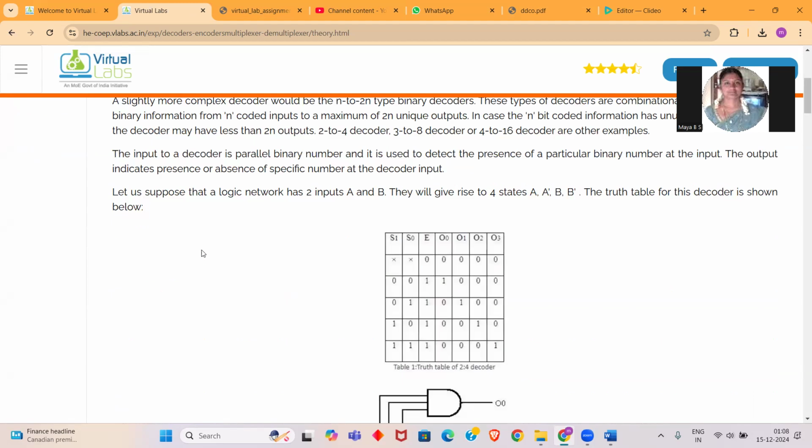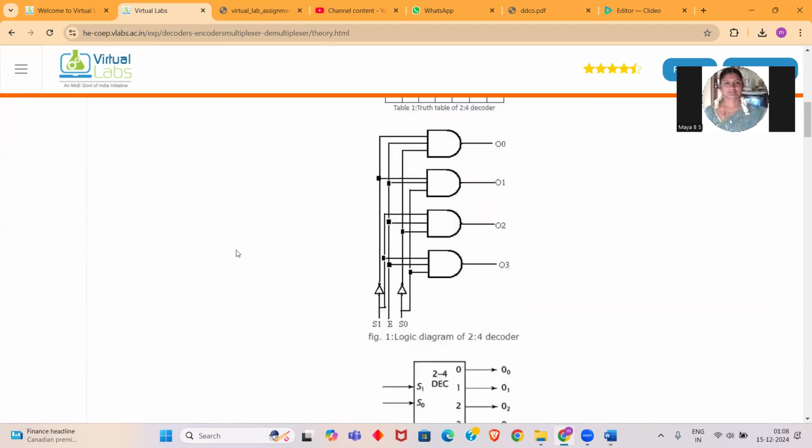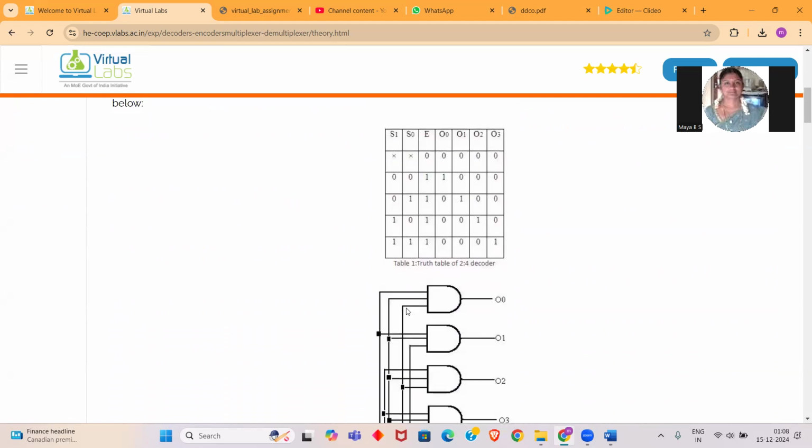And this is the decoder truth table. In that decoder, we have to use select lines. We have to use a 2:4 decoder. I require two select lines because we have four possible combinations: 00, 01, 10, 11. And we have to check the enable pin, because I have to check whether my decoder is working or not. So this is the 2:4 decoder. See, my enable pin is 0. I am not selecting any of the select lines. Is it in off condition? I am not decoding anything.